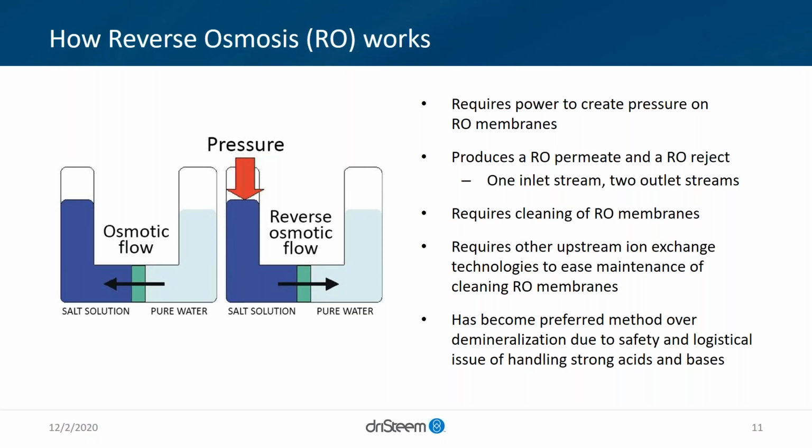Let's see, RO membranes, talking a little bit about maintenance, do require cleaning. The best thing is whether you're out there and you see anti-scalant feeding to prevent scaling, or if you're using a softening technology, that really helps minimize the amount of times the membrane needs to be cleaned. The other aspect to this is if you choose not to clean it, you can replace membranes. I know a couple different places prefer to do that. Essentially, then they don't have to handle the cleaning and the salt, etc. We definitely recommend pre-treatment though regarding softening.